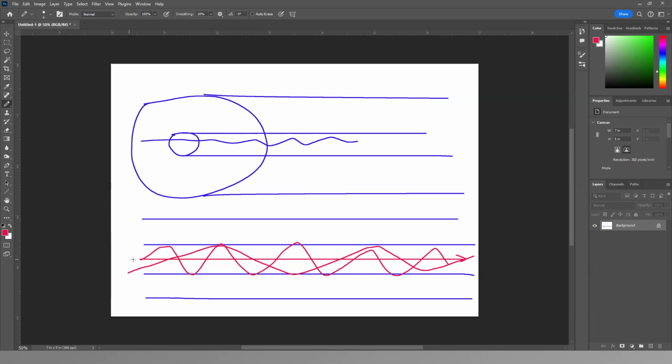Obviously the one mode that goes straight, that light is going to get to the other end the fastest. Any other modes are going to take a longer distance to travel, and they're going to arrive slightly later. As a result you get dispersion. When you have a nice and sharp signal on one end, at the other end you're going to have a kind of dispersed signal. That is going to affect the frequencies you can use, how fast you can transmit those light pulses.